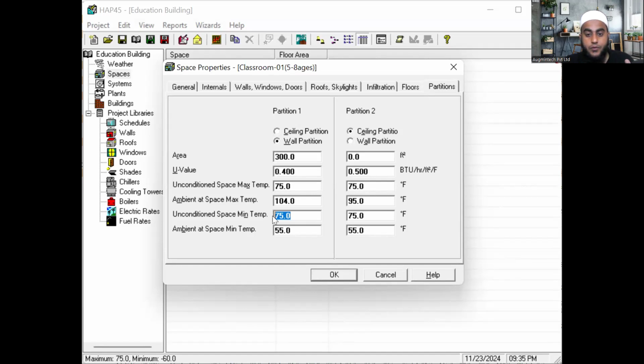In cold climate, I am talking about. So how much? Tell me, please. If the ambient temperature in winter or cold climate is 55 outside, inside the room the temperature will be a little bit high. So how much high? As per ASHRAE, 5°F. So just take it as 60.